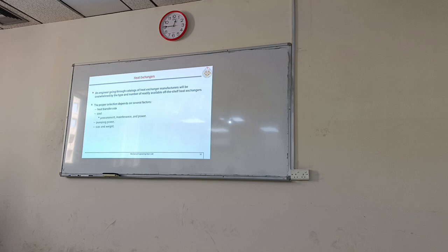Okay, so here is a general criteria to select heat exchangers. It depends upon, of course, Q dot, the main thing, cost, procurement, maintenance, and power requirement, pumping power, size and weight, type, materials.